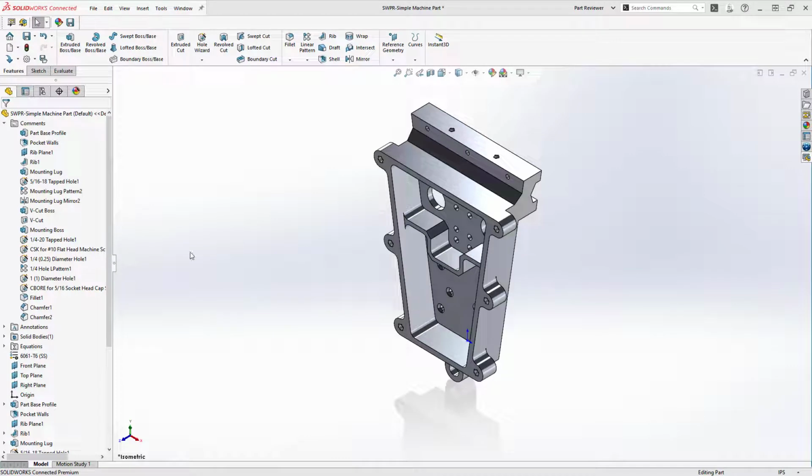There are also mouse gestures to use. Using the right mouse button, hold it down and slide slightly to call up the mouse gestures. Mouse gesture ring is customizable and context sensitive like the S key. I'll go into each feature in detail when I recreate the part.